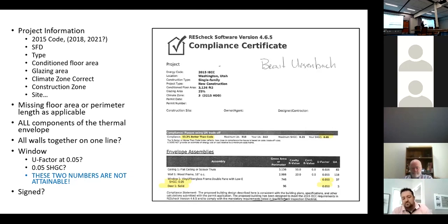The U factor on a window takes into account the whole assembly, the glass and the frame. There's big buildings all over the country that were modeled with 0.25 glass, and these are buildings that are almost all glass, when in fact the U factor was 0.5 or higher. So what would that do to the model? The energy consumption is where? Doubled. We doubled the conduction through the windows because we put in a factor for just the IGU, the glass units, not accounting for the frames.